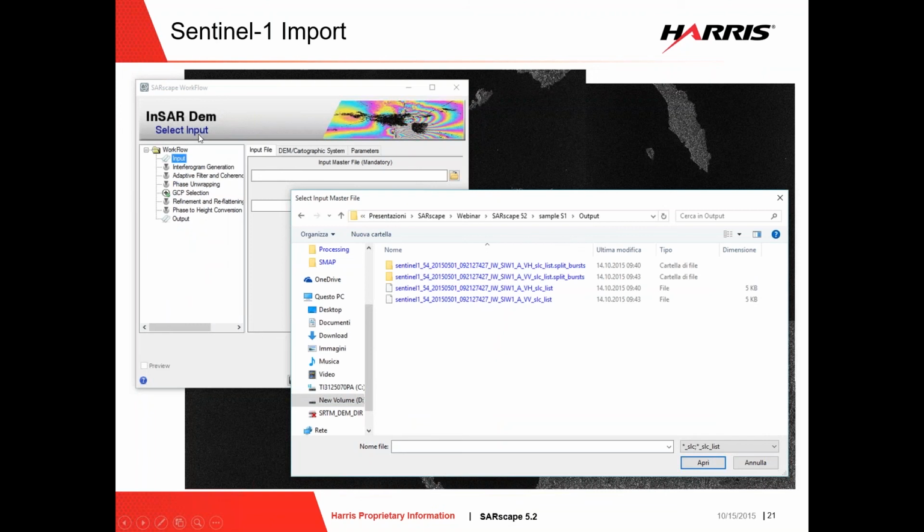So basically, if we have a look at the interferometric workflow, for instance, one interferometric module, and I started here, for instance, the InSAR digital elevation model generation workflow, and if I select input file, I am allowed to provide a single look complex as well as a SLC list file as input. So if I provide a SLC list file in input, all the single bursts will be used during the interferometric processing.